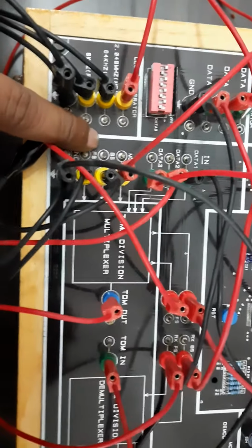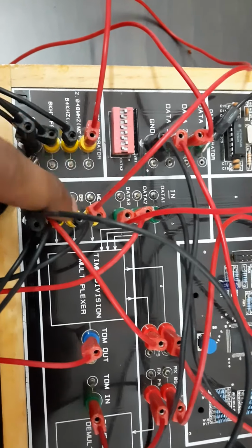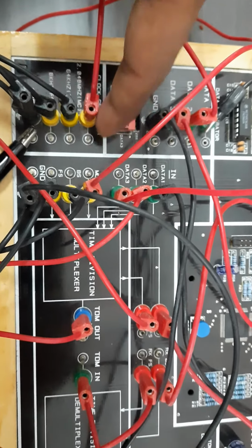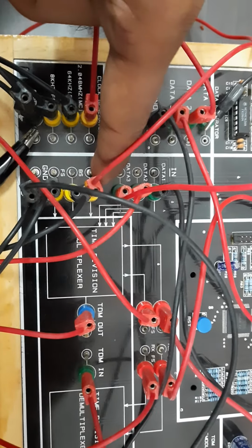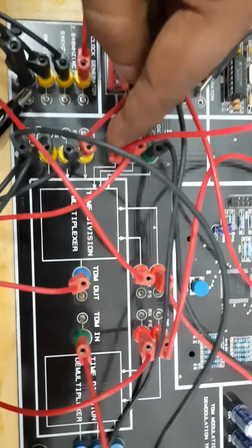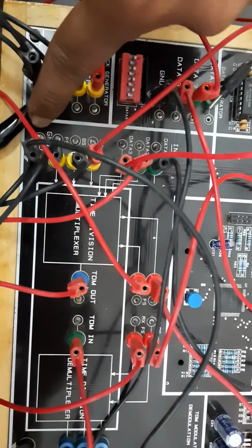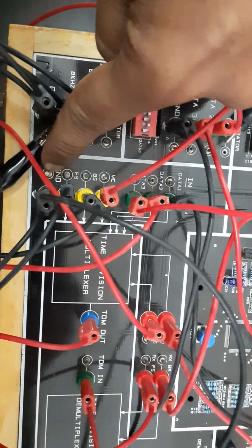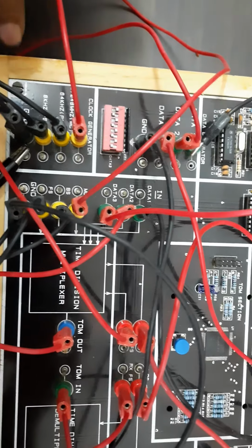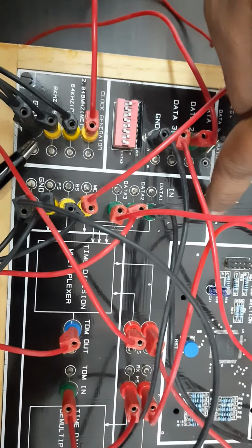Coming to the section below, again we have an internally generated clock, that is the yellow color, BS and FS. These three have to be synchronized. Can you observe the yellow color knobs? Yellow color knobs to yellow color knobs you need to connect, so that the generator as well as this TDM block are synchronized with the help of BS as well as FS. Again we have one more ground here. The main important point here is the ground in the data generator, the ground in the clock generator, and the ground in this TDM input section.